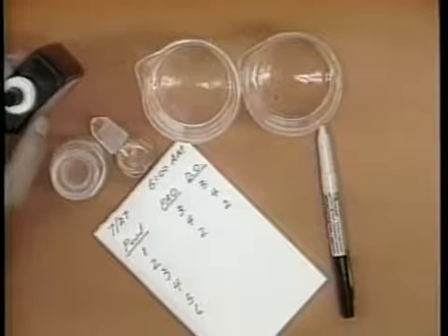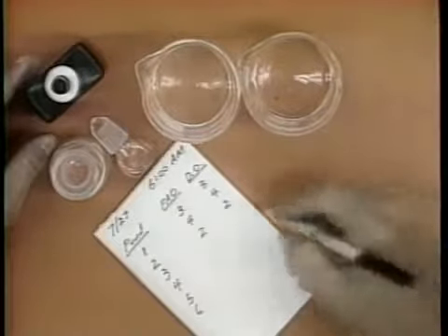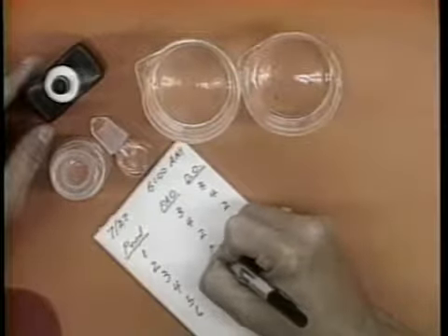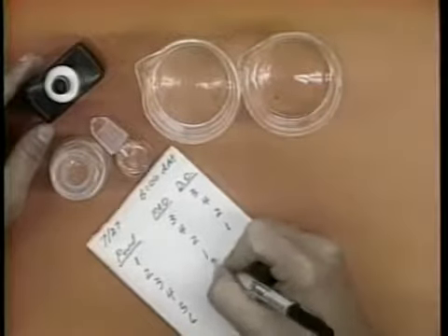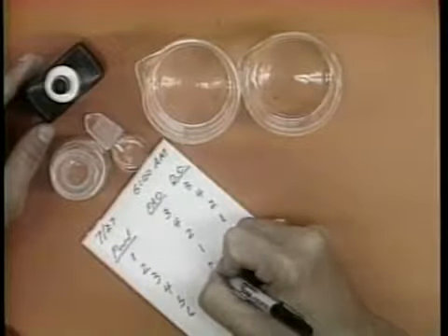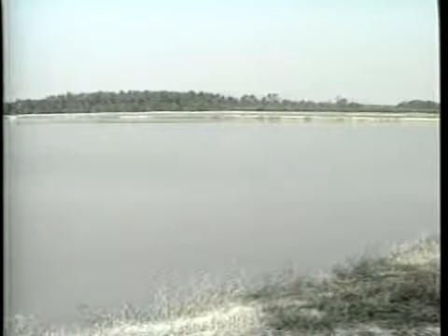During the summer, dissolved oxygen should be recorded twice daily, ideally at dawn and dusk. Records should be kept, which may indicate trends which may affect fish if corrective measures are not taken. During the cooler months, where there is less danger of oxygen-related fish kills, measurements may be reduced or discontinued, depending on the stocking density of the pond.